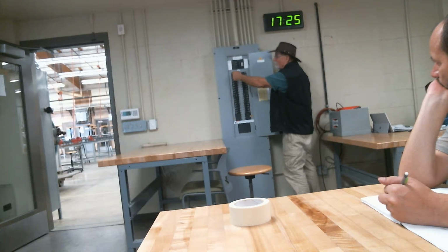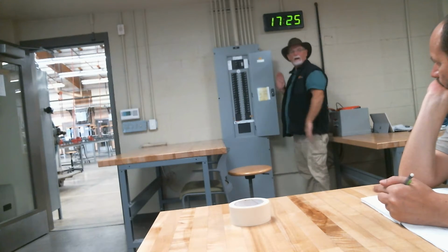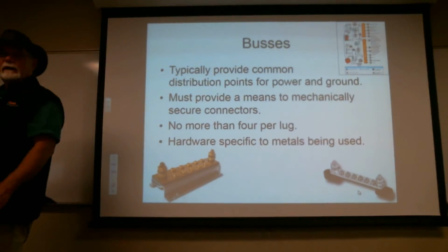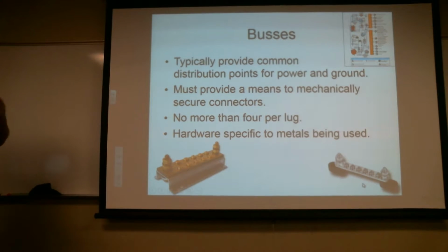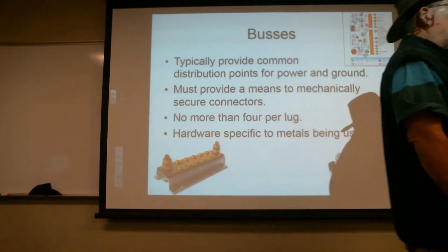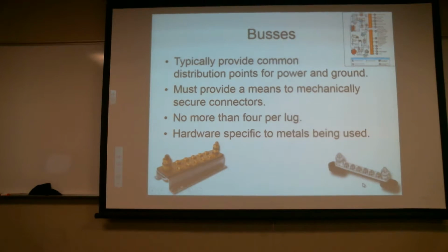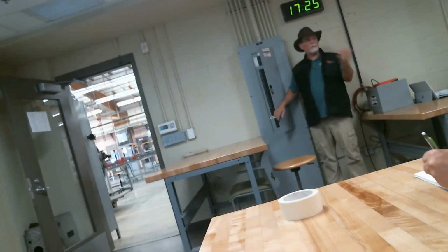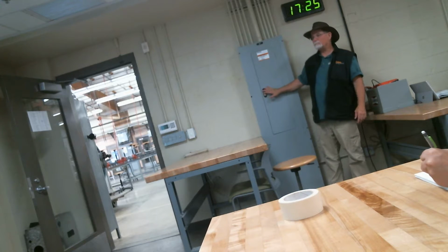This will be staggered off one. This will be B, B, C, back to A, all the way down, so that I then load share all the way across. So really, in truth, that's three different buses all combined into one box. Because in this case, the electricity we're using is three-phase AC. And in cases where we need two phases or all three phases, we gang the circuit breaker together so that if any one side decides to go, it's going to kick the rest of it out.